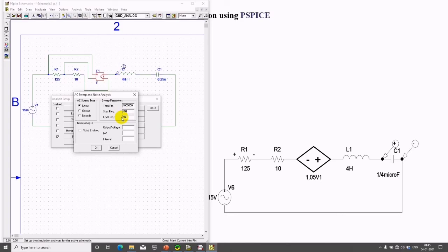Here we gave the starting frequency and ending frequency as 158 and 160 because on theoretical calculation we got F1 and F2 as 159.08 and 159.22 respectively. So I entered the nearby values of F1 and F2 as starting frequency and ending frequency respectively.